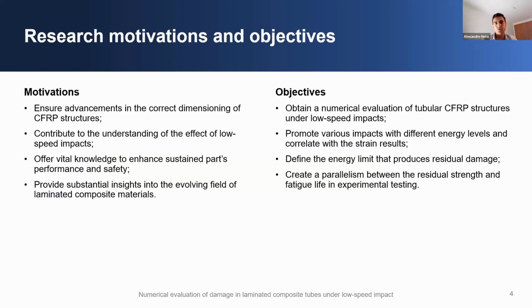Objectively, I wanted to perform a numerical evaluation of composite tubes under low speed impacts by promoting various impacts with different energy levels to correlate with the strain results that we'll see later. For the specific layups I will study, I will define the energy limit that produces residual damage, and in future work, I will create a parallelism between residual strength and fatigue life in experimental testing.